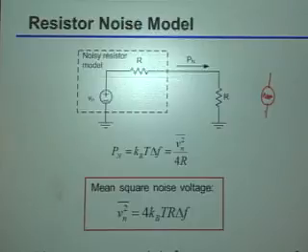Okay? So in particular, you should be very careful that, for example, if you had two noise voltages in series, and you just so happen to draw them like this, if those are two independent noise sources, you had better not cancel them out. Okay? They actually add, and they add in variance. I'll show that in one more second. Okay? So just keep that in mind, because that's a very classic mistake that gets most people when they first look at this.